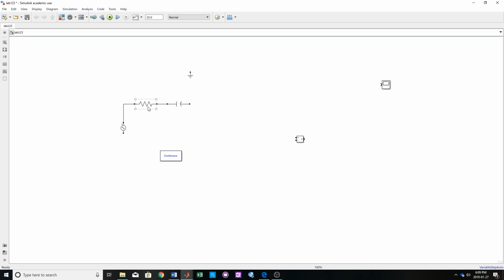So let's say you want to also, in series to this, add a bunch of resistors. I don't know. So what you can do is just literally copy this and paste a few of these. Okay, you have another resistor here. And then if you want to rotate something, you can just select it and press Command or Control R. It's going to just rotate it around like that. You can do whatever. All right, so let's say you connected that like here, for example. Okay, and you connect it there.